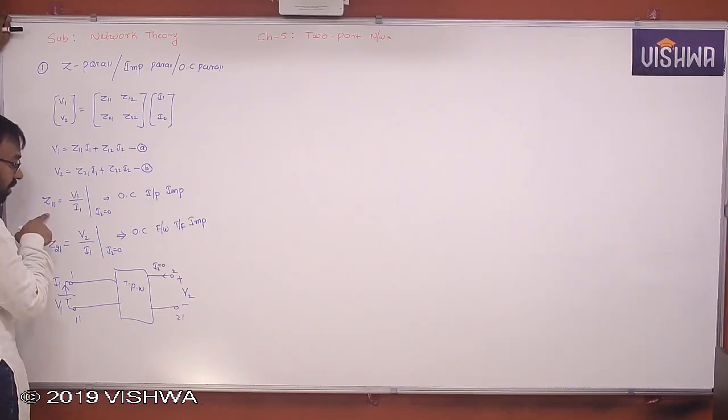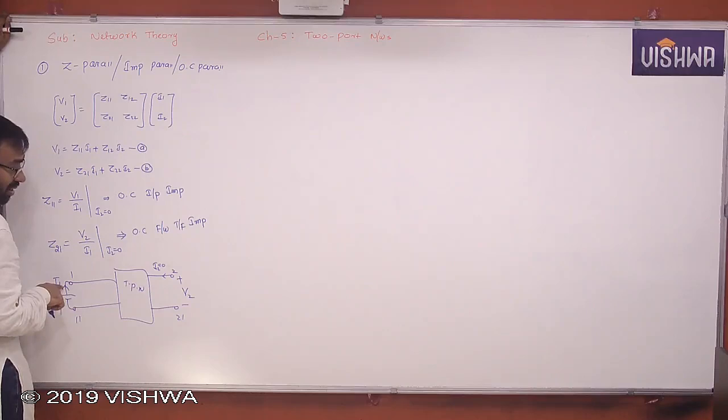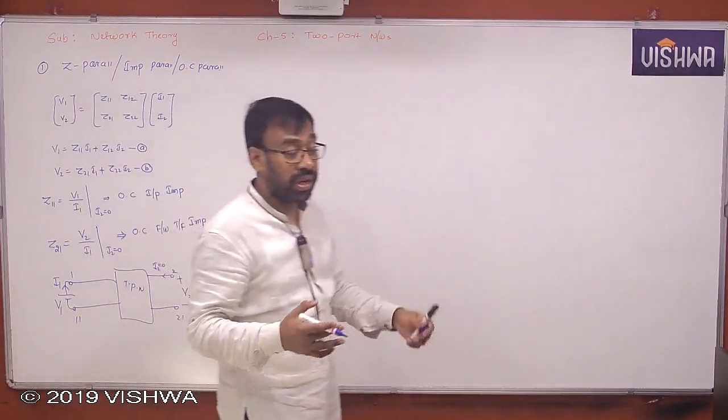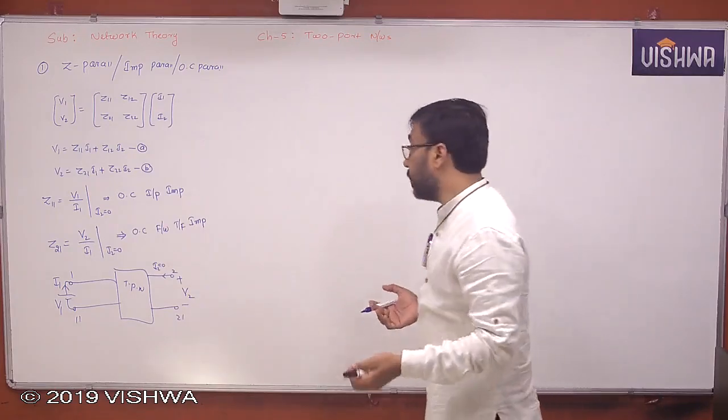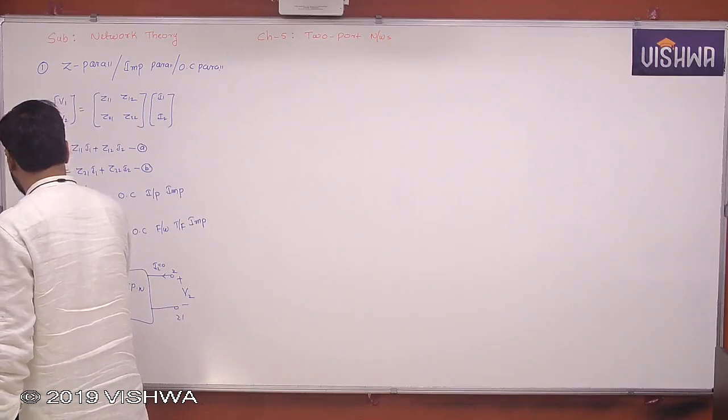You will get Z11. Find the ratio of voltmeter reading V2 by ammeter reading I1 here, then you will get Z21. This is how you determine the parameters of any given two-port network. Understand? Okay. Well, now this is what when I2 is 0.